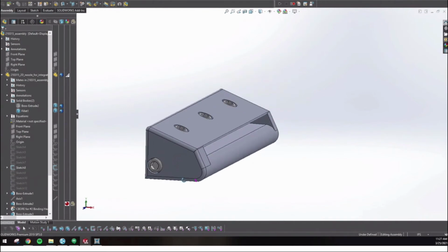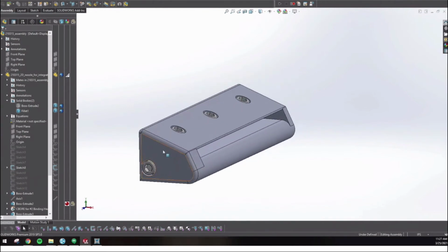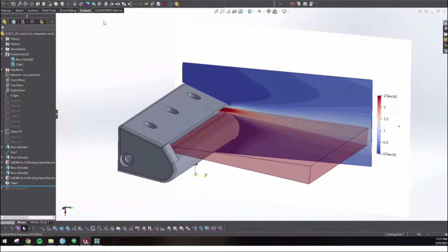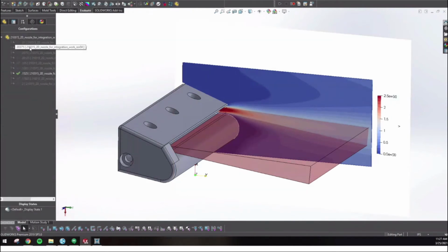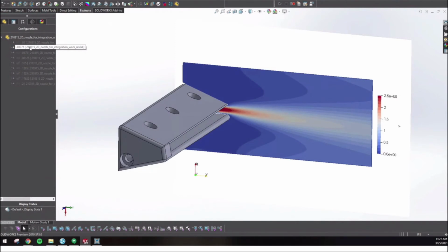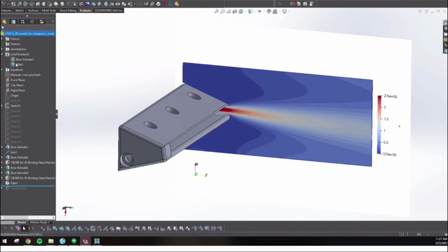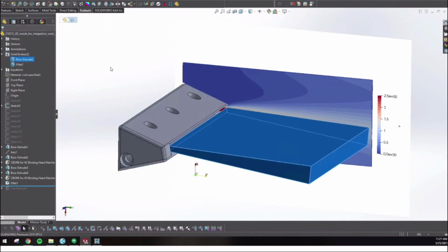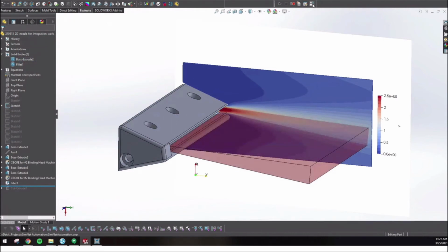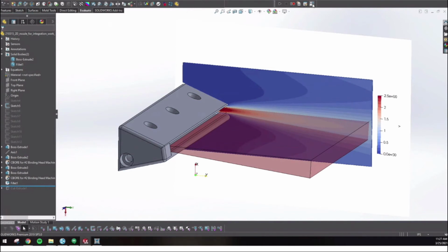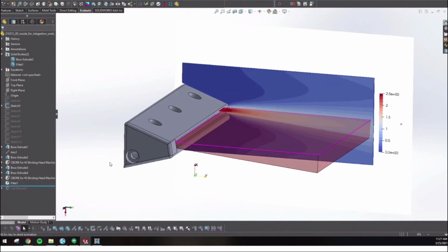So here we've got the assembly. We're going to move into the component where the trailing edge is defined, and then we're going to adjust that radius. We'll turn on the jet angle body here so that we can see the jet. And then as you watch, we go up and click on our button that fires off the SolidWorks macro. And then you saw that jet angle change. Now we're going to move into a side view and do this again.